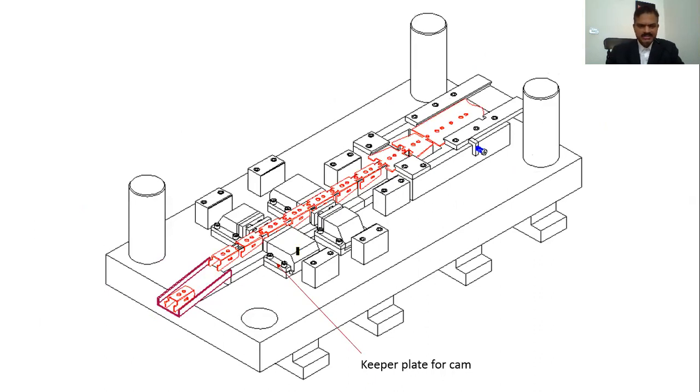And just like you have put a keeper plate for the stripper so that the stripper will not move up, you need to provide the same keeper plate or cover plate for the cam also, otherwise the cam can lift up, right? So that's what you see in this.